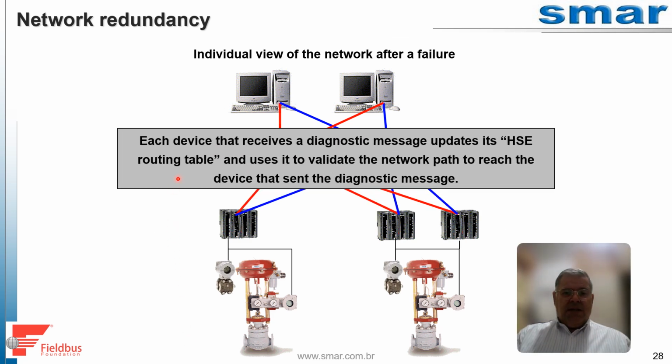Hence, every device that receives a diagnostic message refreshes its HSE routing configuration and applies this information to verify the network route taken by the device that transmitted the diagnostic message and determine its path correctly, thus making the redundancy of the system.